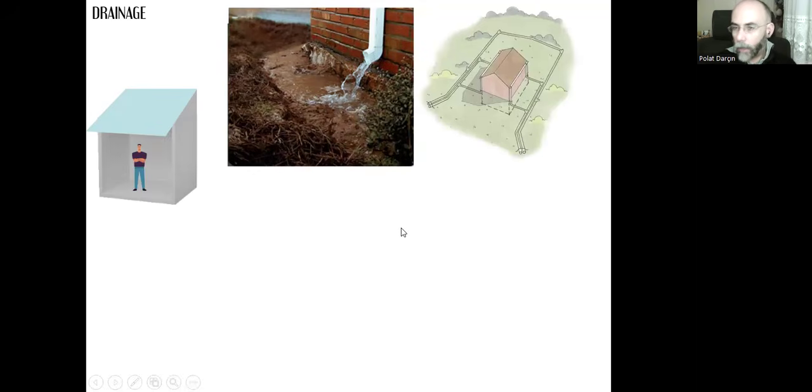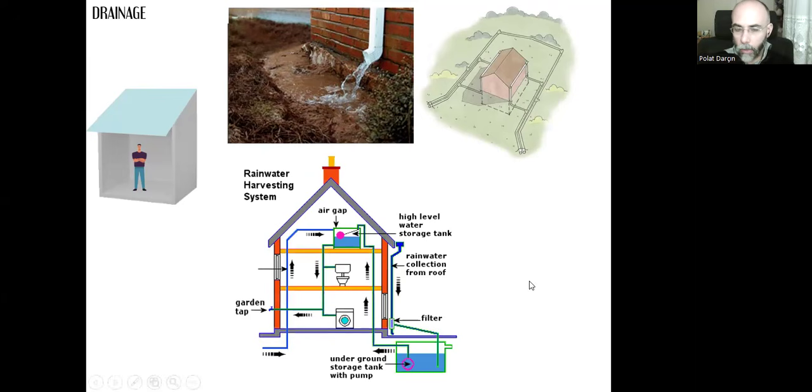Instead, we can connect the downspouts to a stormwater collection channel, and we should never connect the downspouts to sewer, because if it rains so much, if there is this excessive water, then it will cause the sewer system to create a problem. You will have this return at your toilets. That can be very dangerous.